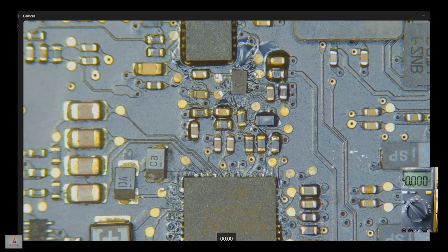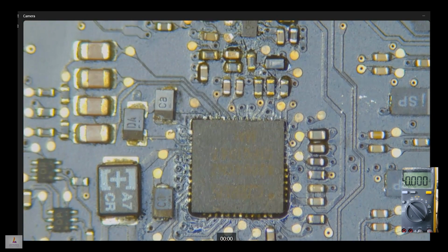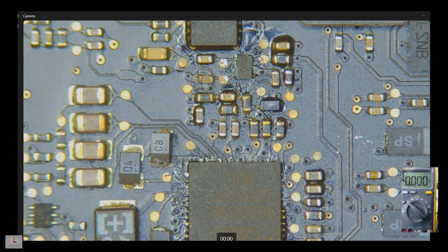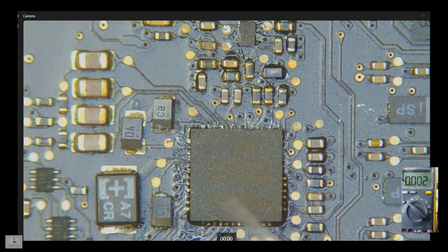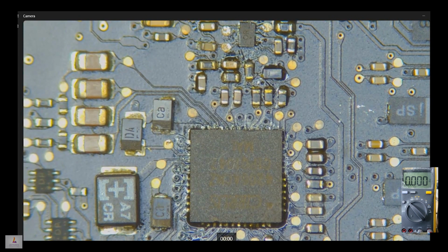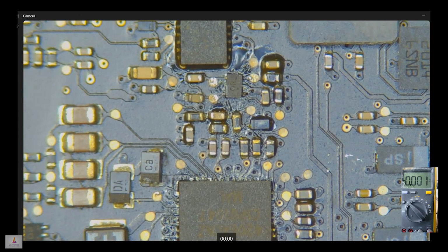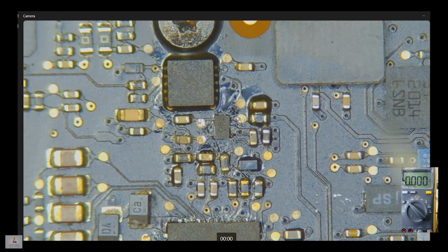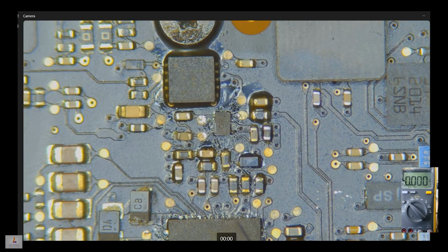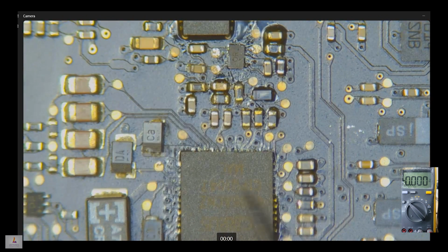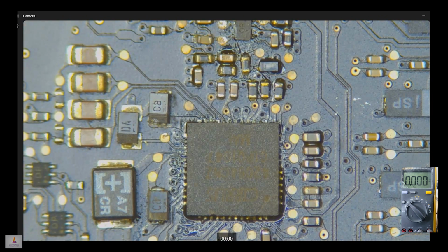After getting my 4.5 volts, I still wasn't getting any audio. So I ended up replacing the audio IC also, as you can see, flags around this. So it became kind of like a rabbit hole, okay? It started with replacing this power regulator IC, replacing this capacitor, and then replacing the audio IC. Then eventually we started making progress.